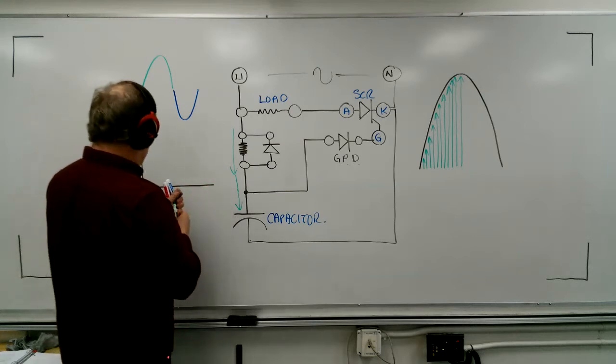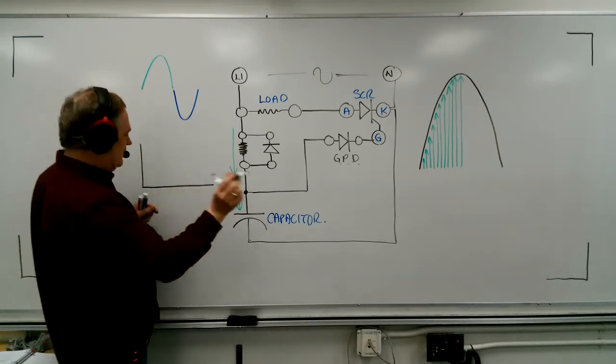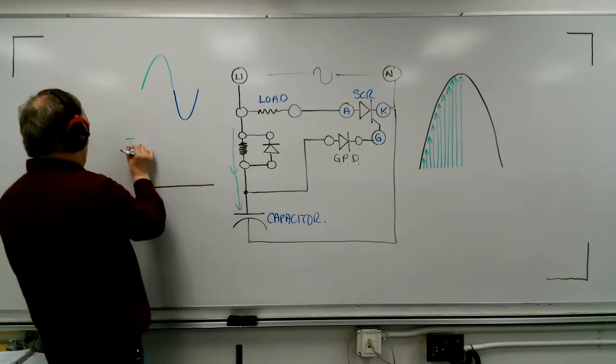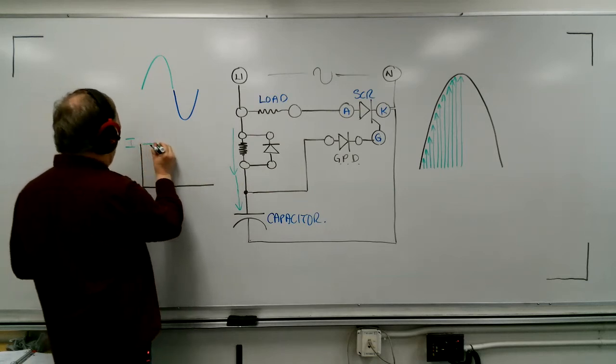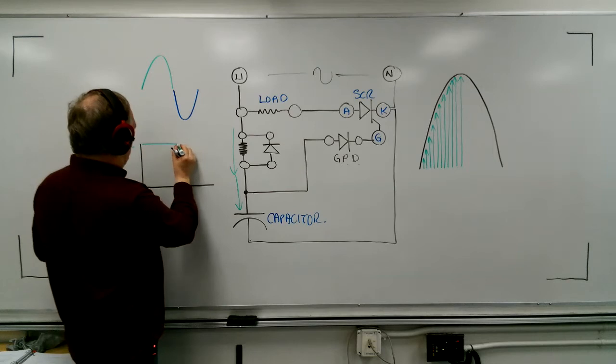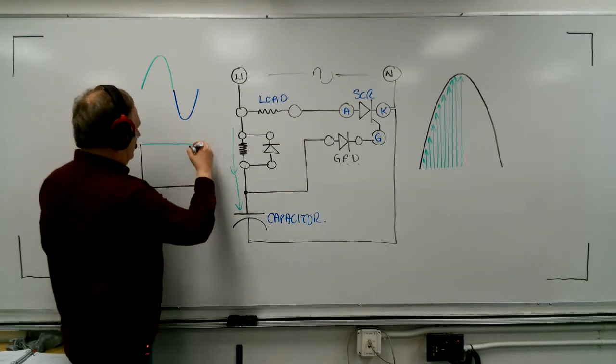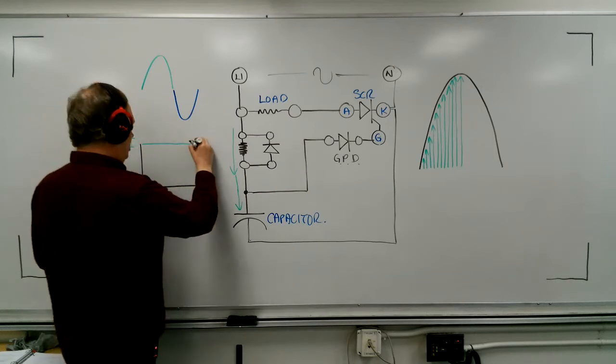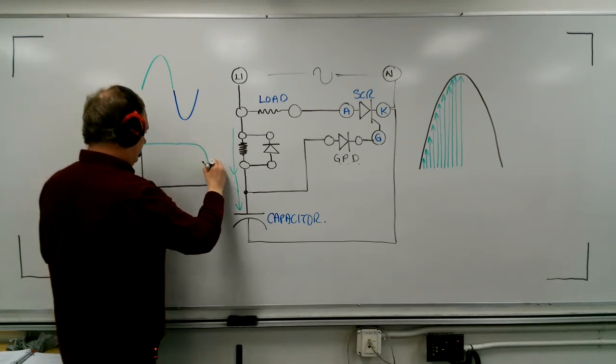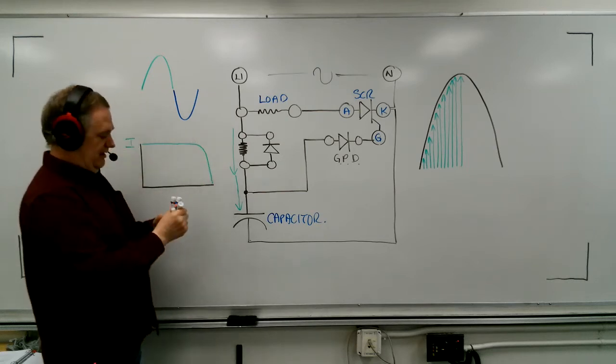And to begin with, at the instant you start charging a capacitor, the current, I, flows at its maximum level, like this. And when you get almost to the end, just to the point where it's full, all of a sudden the current goes like this and it drops off to nothing.